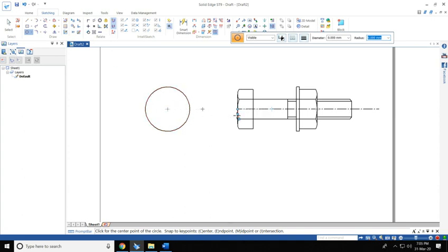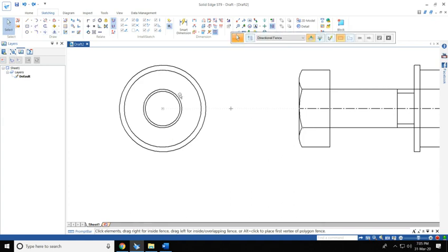And then you'll have another circle of 40, correct, the nut, and then you'll have another circle which would be hidden at 20 mm dia, and then the thread, which is about 18 mm because it is 2 mm apart, correct. So these two would be hidden, dashed lines,